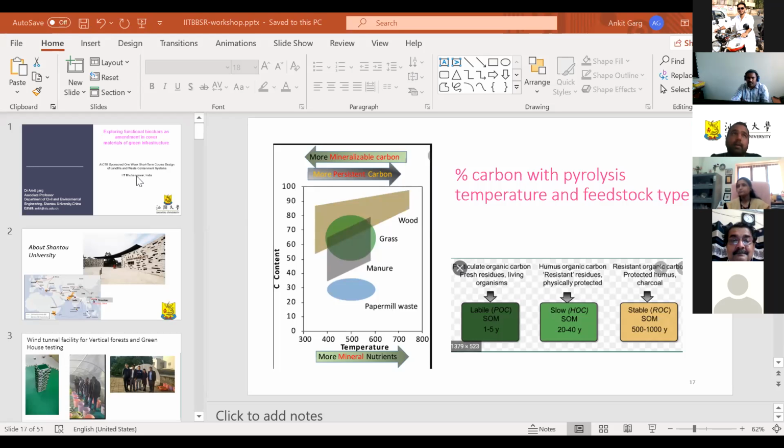With bentonite, there have been studies published. Biochar can, in one way, reduce the swelling of bentonite to some extent, and it also helps to soak up some contaminants. But biochar is not a very active material, especially if you're talking about hazardous waste. So I do not think biochar can be recommended for that part. But if you only want to contain swelling, it's okay. If you want to think about hazardous waste, I think no.